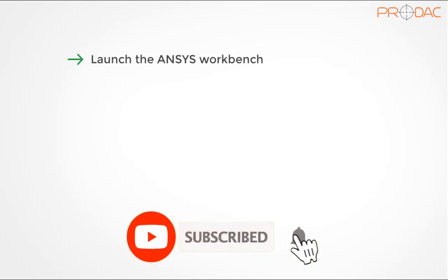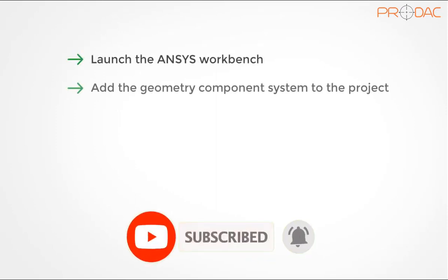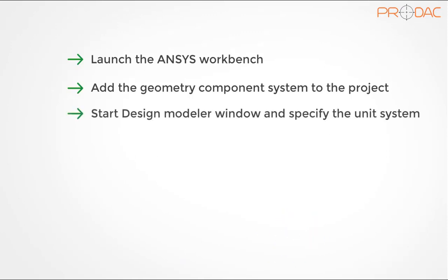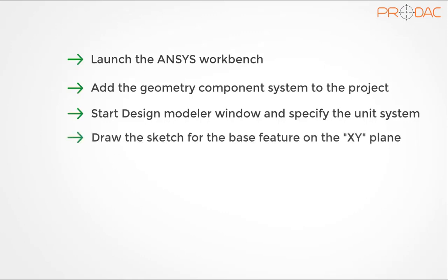First, launch the ANSYS Workbench. Second, add the geometry component system to the project. Third, start design modeler window and specify unit system. Fourth, draw the sketch for the base feature on the XY plane. Fifth, create the base feature.